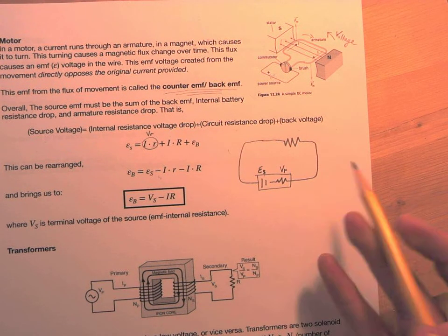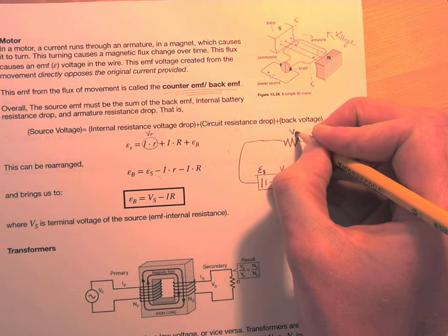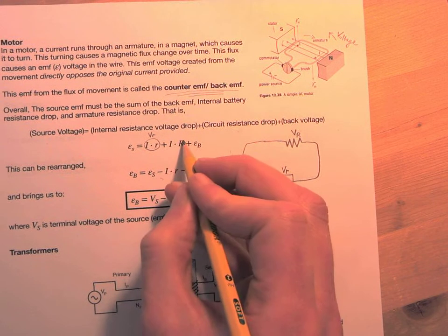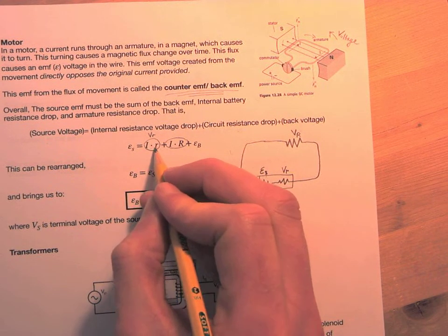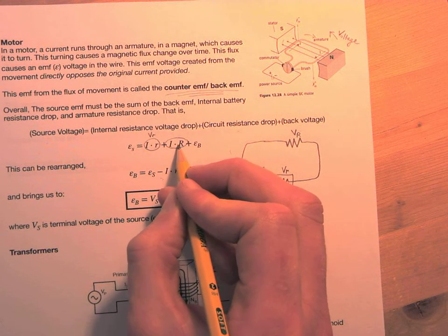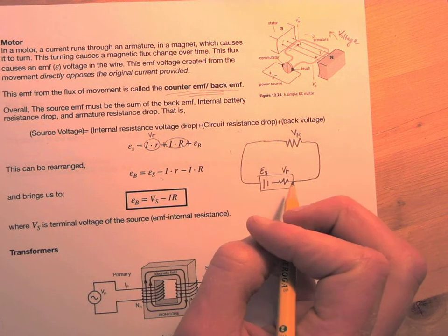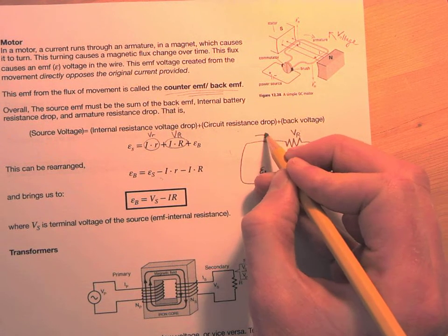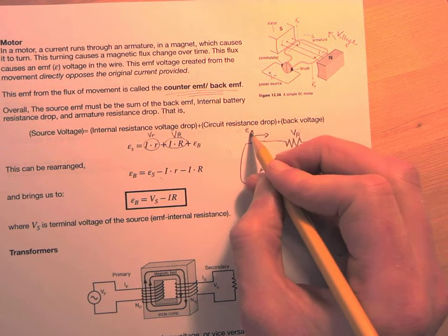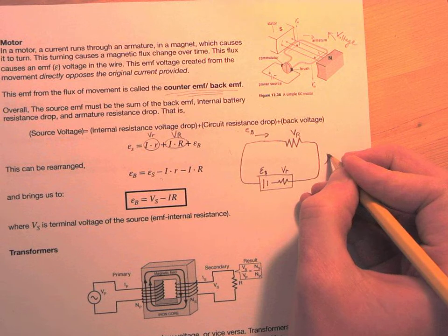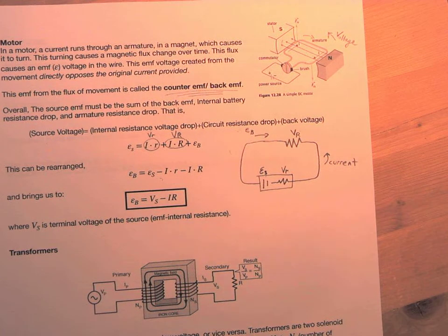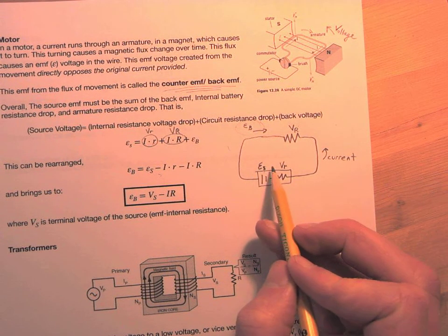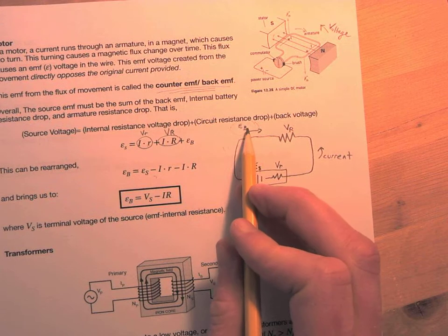And then you go around, and this part here is your big voltage drop from the armature, because it's a resistor, and that's how much gets dropped from it. It's the same current going through there, since it's a series circuit, but this time the resistance is a big R, generally a bigger resistance than the internal. This is your voltage drop through the armature. And then, from the movement of the flux, you're also going to have some back voltage working against your current, and that's going to cause another voltage drop. So essentially you have all this juice coming from the battery. It drops a little bit of voltage there, drops more voltage there, and drops some voltage there.